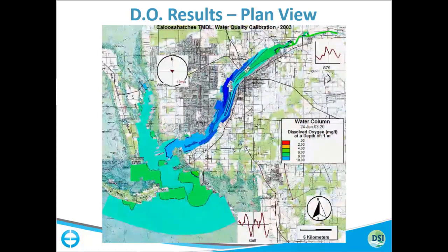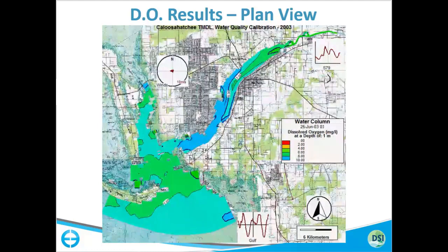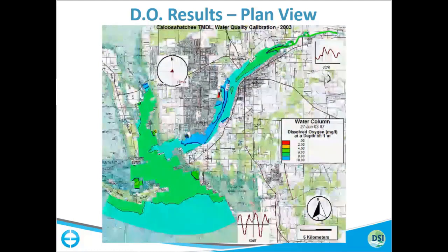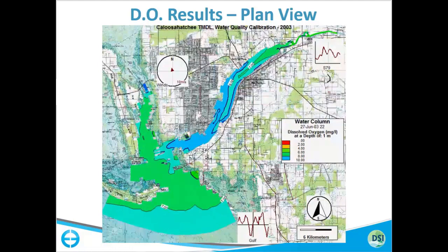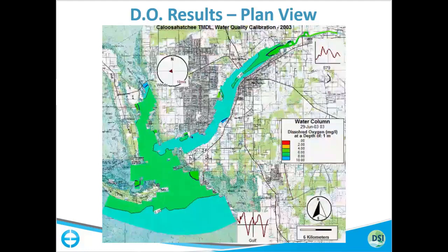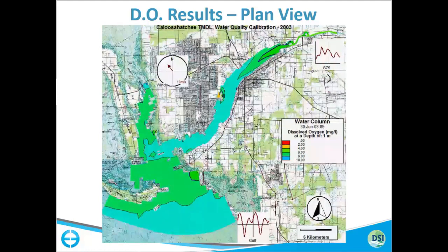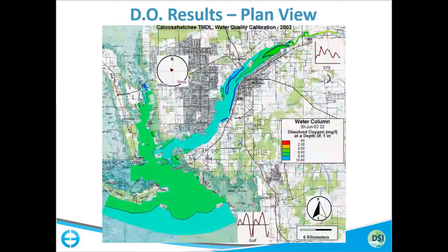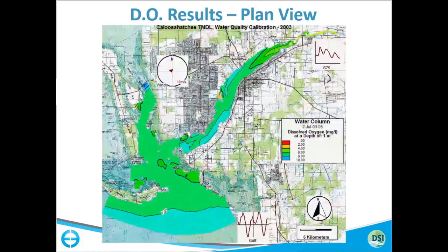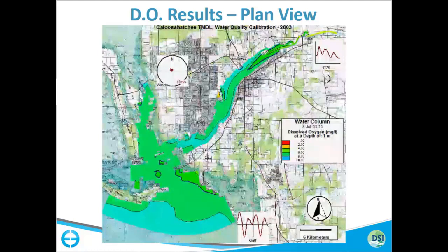And another thing you notice here, it's calculated at the depth of 1 meter. So EFDC Explorer allows you to extract the values at certain layer or certain depth. So if you're just interested in layer 1, then it can be at different depths for different cells. For example, in water quality, people usually look at a certain slice. So when you measure the data, you just measure from top to certain values, right? So it's a nice way to look at what's going on at that particular depth in the system.